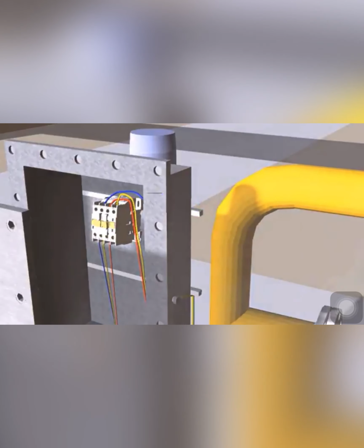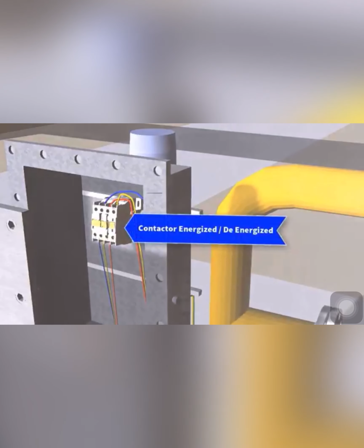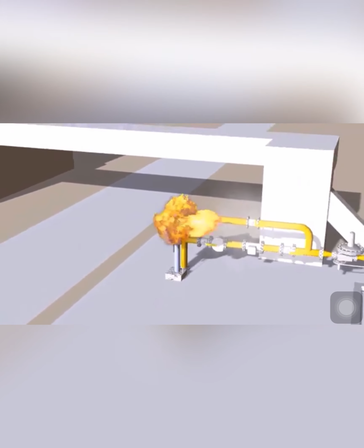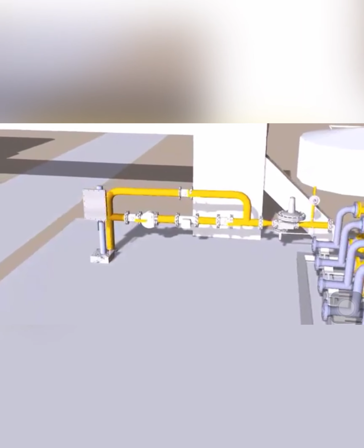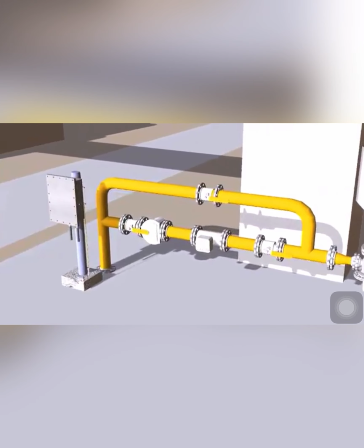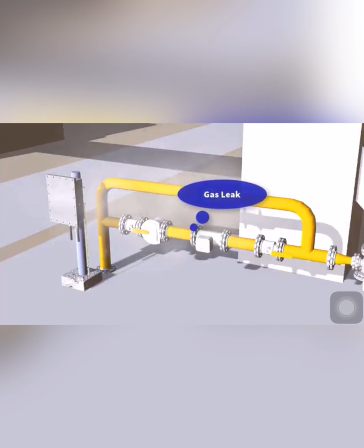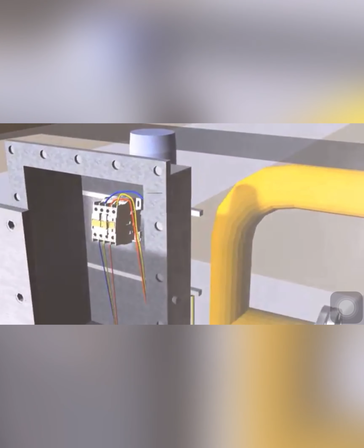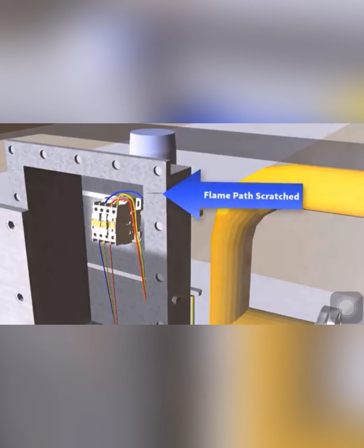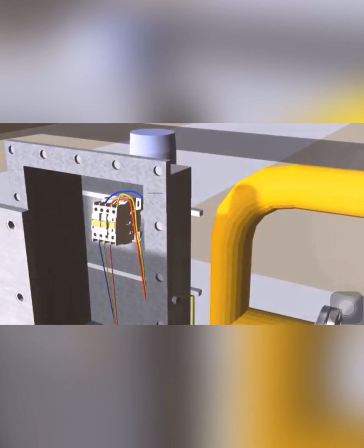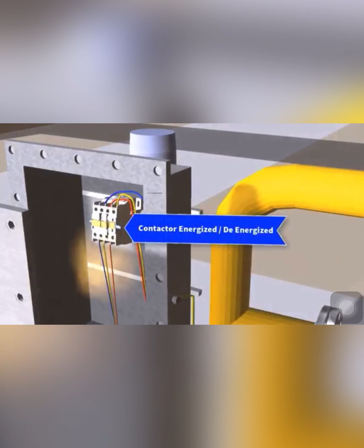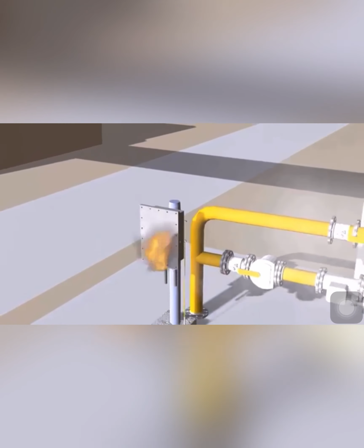For the secondary explosion protection, if, despite primary explosion protection measures, it is possible for a hazardous, potentially explosive atmosphere to form to a degree that requires measures to protect employees against explosion hazards, the ignition of this hazardous, potentially explosive atmosphere must be effectively prevented. All possible sources of ignition are evaluated and the appropriate protective measure applied. Effective sources of ignition on equipment and installation can, for example, be prevented using this type of protection corresponding to the necessary level of protection.